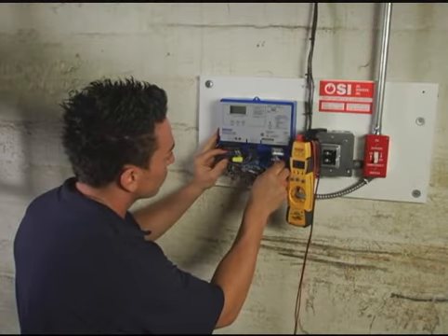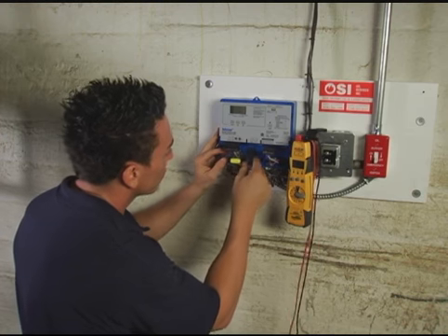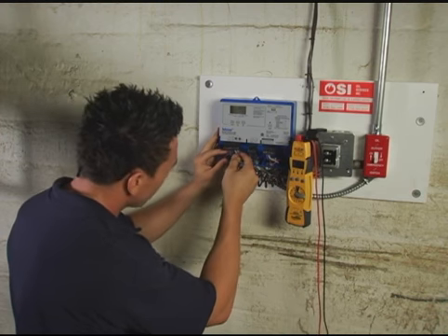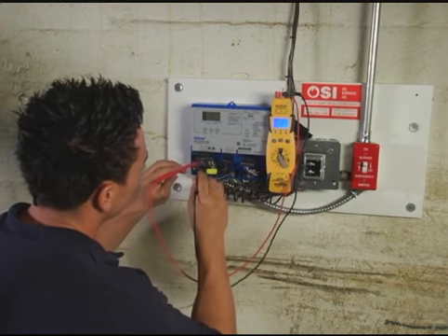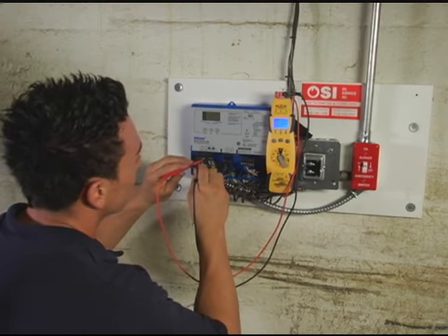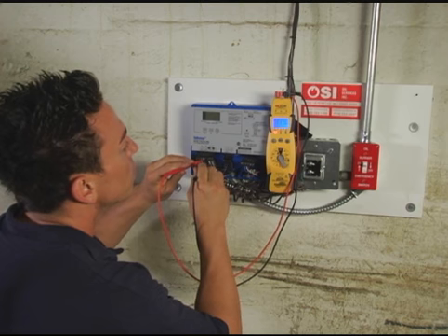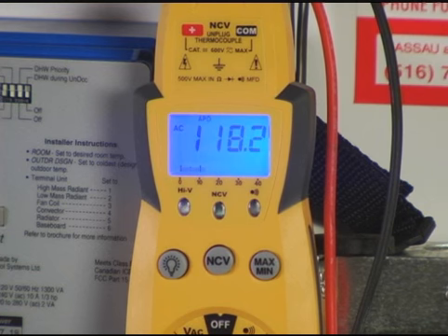Before testing the power supply, make sure exposed wires and bare terminals are not in contact with other wires or grounded surfaces. Turn on the power and measure the voltage between the power L and power N terminals using an AC voltmeter. The reading should be between 108 and 132 VAC.